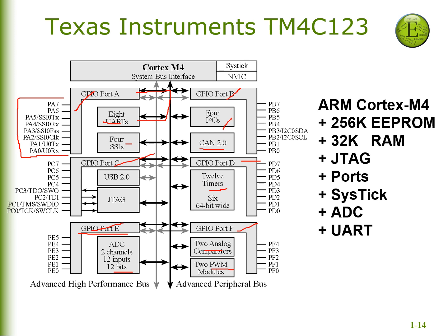And exactly how to configure the role of each port pin remains a topic of our future lecture. Here again, the thing to notice is that there are 2 separate buses: the advanced peripheral bus that connects the microcontroller with the ports as well as the internal modules, but that is a bit slow compared to the advanced high performance bus that connects the microprocessor directly with external port pins.